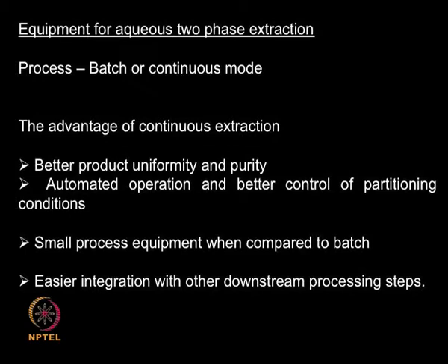We can use batch, we can use continuous, just like we are using solvent based systems. Continuous has a lot of advantages when compared to batch, but the advantage of batch is you just use a very simple tank, you mix the two systems, let the two phases separate, and then separate them through gravity, whereas in a continuous system you need to have many equipments, many controls and so on. But then the advantages are tremendous.